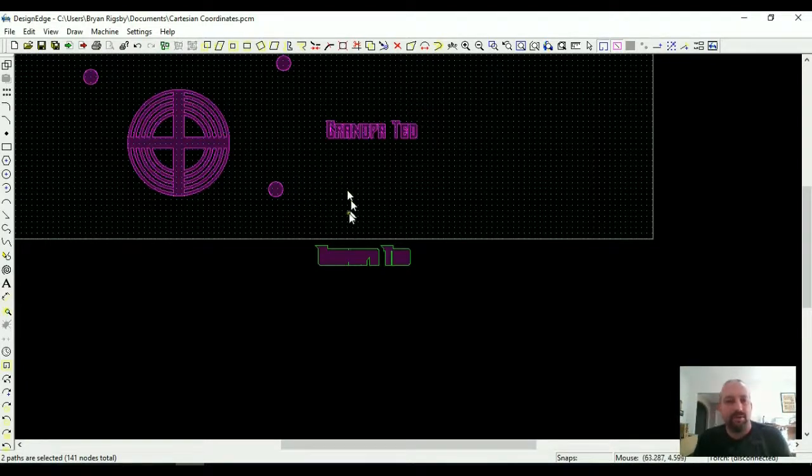But now I'm going to move this offset box I have, and from my move from point, I'm going to pick this center of this circle that I made so I have a reference. So now, as you can see, when I move that around, the pointer is still up to the left. That's just like having this on a piece of paper and saying I want to grab it from this corner of the paper and match it up with this corner of the paper. So I can put it right back where I wanted it by pushing C for center snap and snapping it to the center of this reference circle up here.